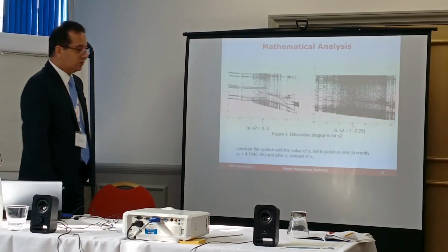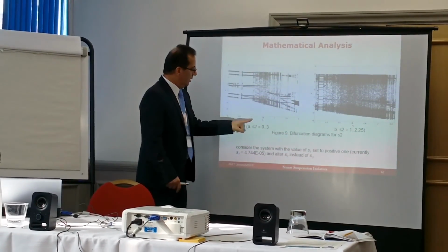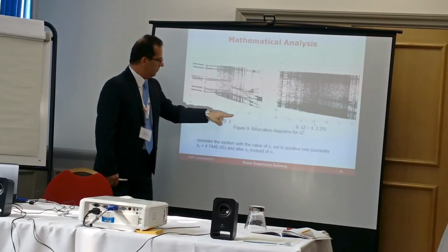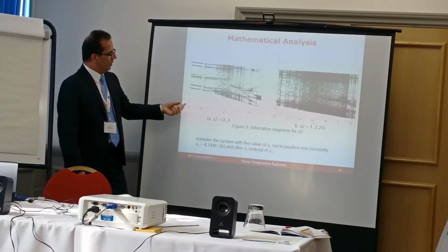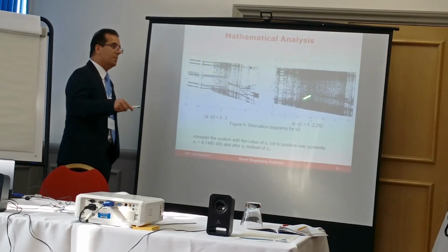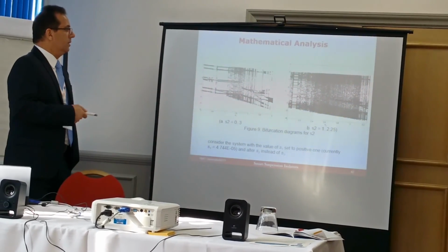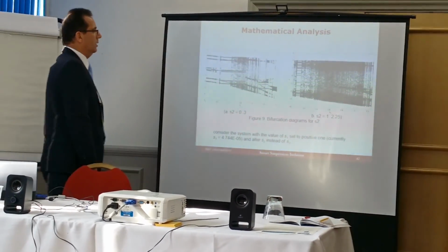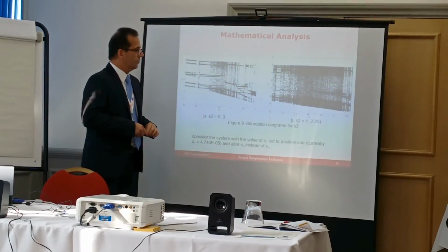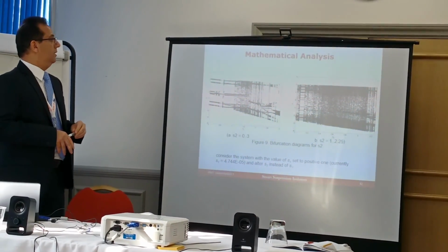But when we try to change S2, remember S2 was the coefficient of x squared. X squared has a strange effect. And as you can see, this is the bifurcation plot, variation of S2, and these are the equilibria. Let's magnify this part and put it here, and as you can see, chaos is happening here. The next step is to go for fast Fourier transform, autocorrelation function and Lyapunov function, to double check the chaos here, and then create the same chaotic motion in the lab.